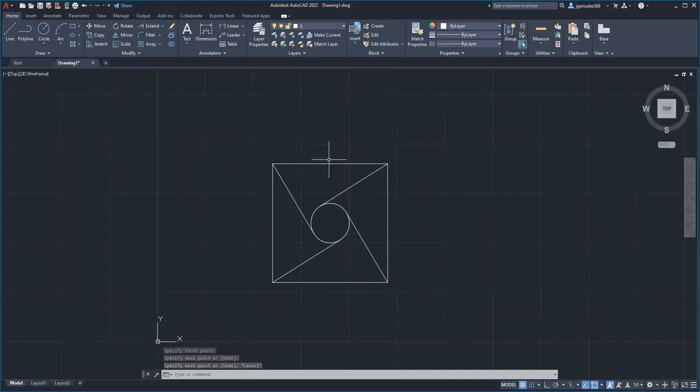Now let's make some more using the midpoints. So we used all the endpoints and connected it to the tangents. Now let's use the midpoints to repeat it. So a midpoint, hover next to the circle, attach it to the tangent point. Midpoint, tangent point. Tangent. There you go, little 007 symbol here.